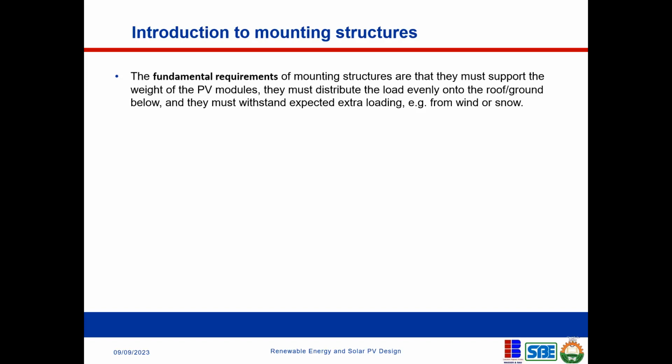Now, most buildings, at the time they were designed many years ago, were not designed to support the extra load that would come from PV panels placed on the building. I'm talking about some buildings that are weak, maybe aged buildings where the structures are not strong enough. So you must consider the supporting structure.